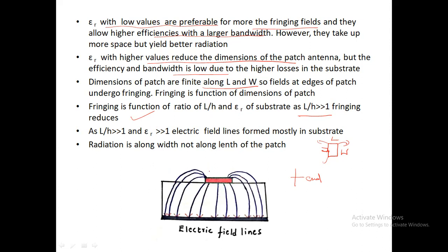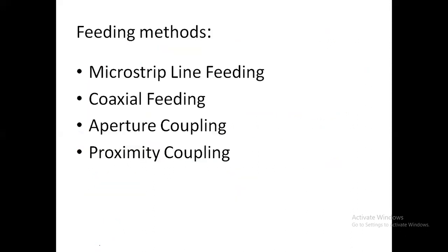So as you go with the point of these patch antennas, the most important thing we need to keep in mind is that the fringing effect should be more. For having the fringing effect in increased mode, the design of length, width, as well as height of the substrate, these three are the key factors, as well as the epsilon value, which should be chosen in a proper way. So for all these things, certain dimensions are given. According to that, the values are to be taken.